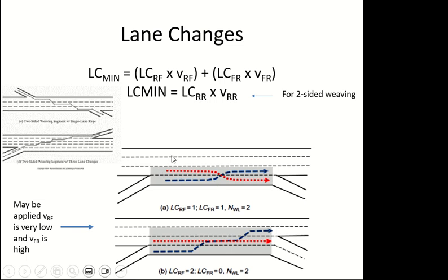But since he was in the wrong lane, not like wrong, he is in the same direction, but he is not in the closest lane to his ramp. So he is making extra lane changes here. So he is still part of the weaving volume, but he was not in the correct lane, the lane in which he should be. So he or she will make extra lane changes.